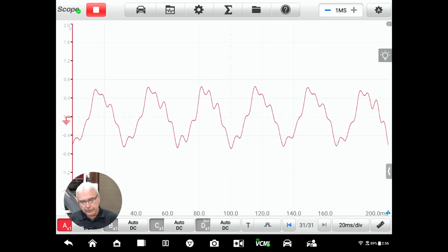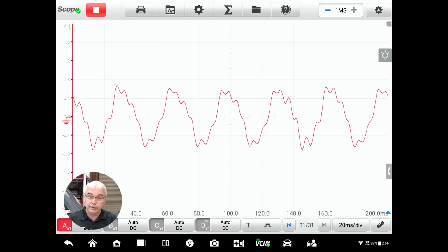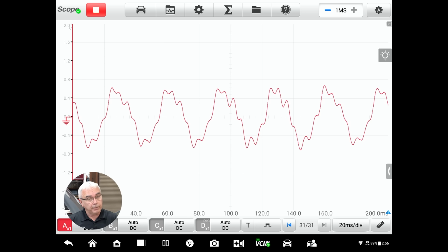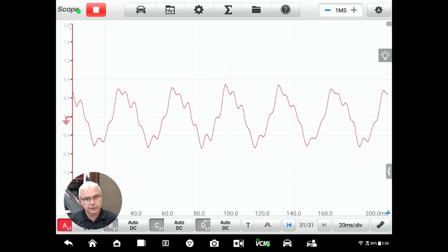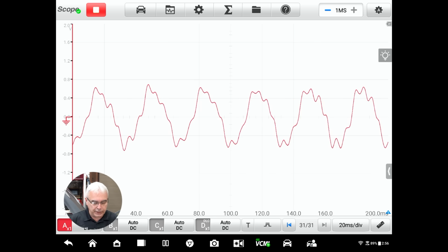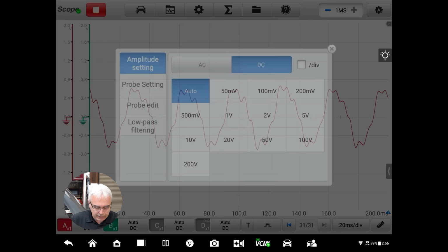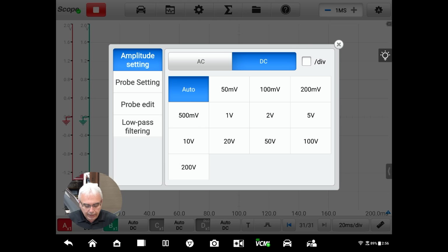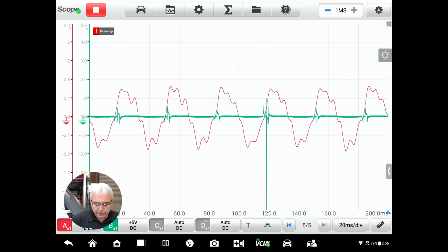Now normally, for training purposes, I would adjust the time base a little bit to just get 4 of these on the screen. But since I'm about to turn on a couple more channels, I'm going to leave it at this time base for the time being and not make the final adjustment until I got all 3 channels up and running. So the second channel I'm going to turn on is channel B, and I am going to say that, hey, let's go ahead and go with a 5 volt pattern.